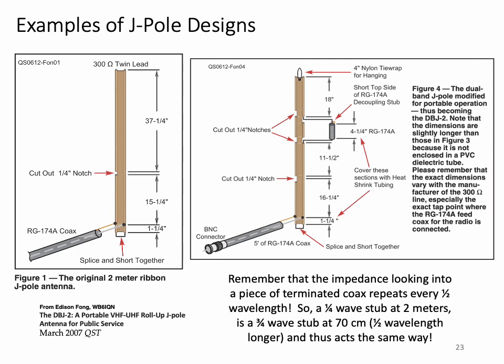We know that a half-wave dipole will in fact operate under third and higher odd harmonics. For the single band design, recall that the quarter wave stub for 2 meters at the bottom, it's this portion right here, will also act as if it's a quarter wave stub for the third harmonic, or 70 centimeters. Instead of a half-wave dipole at the top, though, if we operate this first antenna on the third harmonic, we now have a 3/2 wave radiator and not a half-wave radiator, and that occurs on 70 centimeters.